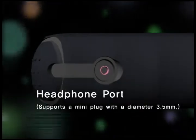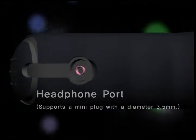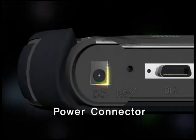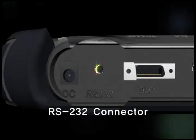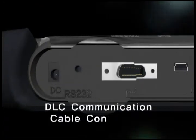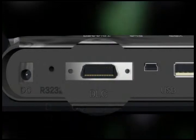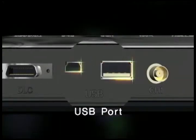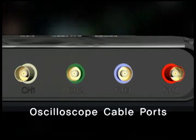On the right side of the device, there is a headphone jack for plugging in a headphone. The external 3.5mm mini plug is supported. On the top side, there are the following items: power connector for power supply, RS-232 connector for connecting with a gas analyzer, DLC communication cable connector used for vehicle diagnosis, USB ports for data download or interfacing with a printer or mouse, and 4-channel scope cable ports used for measuring waveforms.